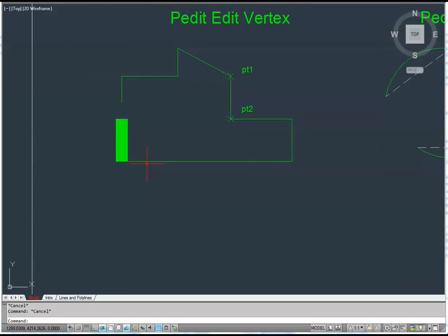Now, just a couple of other things with the straighten part. If I've got a series of polylines, and this is all polylines, if I do polyline edit, PE, pick on the polyline, edit vertice, go to the next vertice, S for straighten, and then it's going next, next, next, next, next, next, and next, and then go. It'll straighten out all of those lines in between. There are quicker ways of doing it, but it's interesting to see how it works.